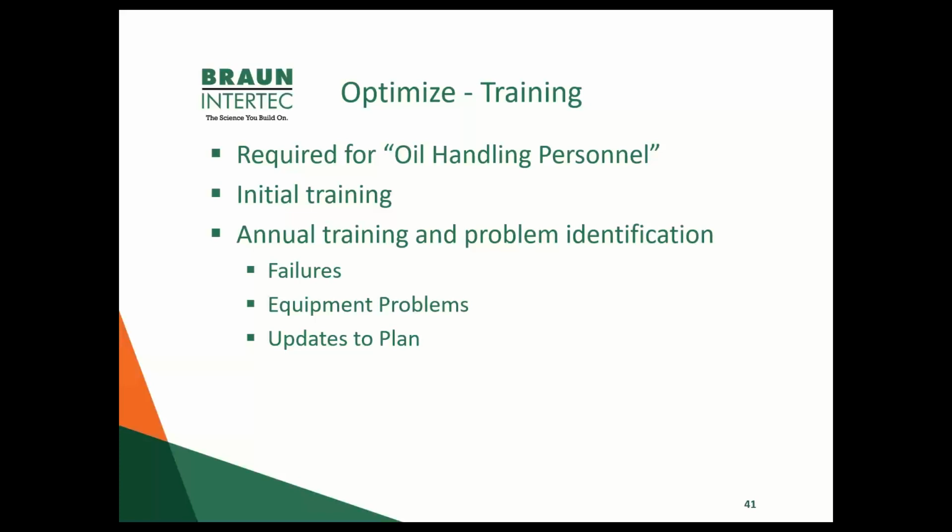Yeah, the SPCC plans are pretty strict. They require an initial training of all your oil handling personnel. So as soon as you have an SPCC plan for a facility, you're required to train your oil handling personnel in the appropriate measures. And then as you add personnel to your facility, they are also required to go through this training. So you don't wait for another annual refresher. They have to be trained as soon as they basically become oil handling personnel on your facility. And then the training has to be refreshed annually.